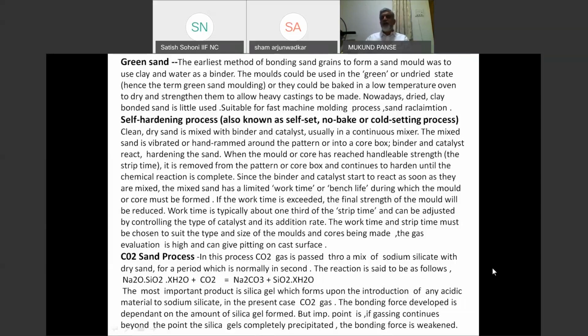However, at around 500 to 600 degrees centigrade, the CO2 sand mixture forms a meshy zone, which is not very hard. If your sand is not going to reach a temperature beyond 500 or 600 because of the configuration of the casting, you can use CO2 sand without any problems of collapsibility, and you can have savings also. However, reclamation of CO2 sand is very difficult. CO2 sand can be completely reclaimed only by a wet process, that is washing of the sand, which is now practically impossible with the quantity of water required.